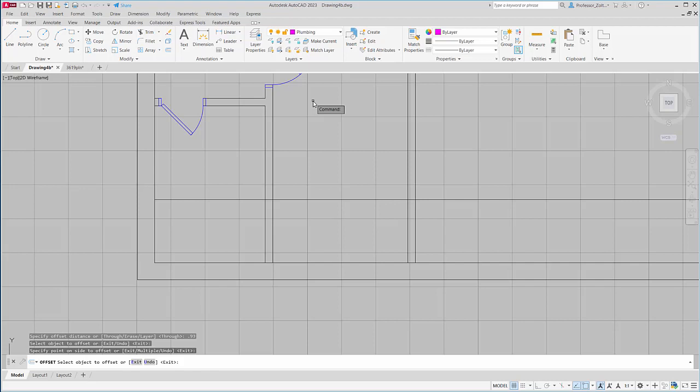And in here is where I'm going to do all my shower fixtures or my bathroom fixtures. So I'm going to replace this diagram here with a rectangle. I'm using the rectangle tool. Again, it has those specific properties that make it a single entity. So when I go to offset, it offsets its entire shape, either inwards or outwards, depending on which side I click on. So I want to offset 0.02,